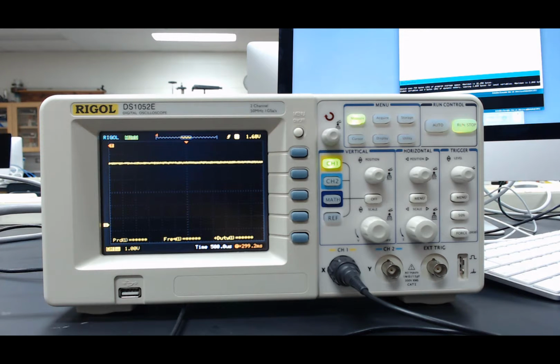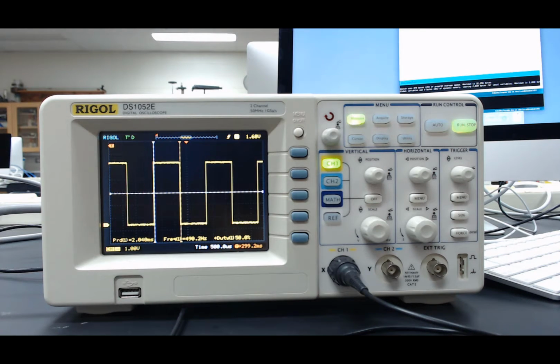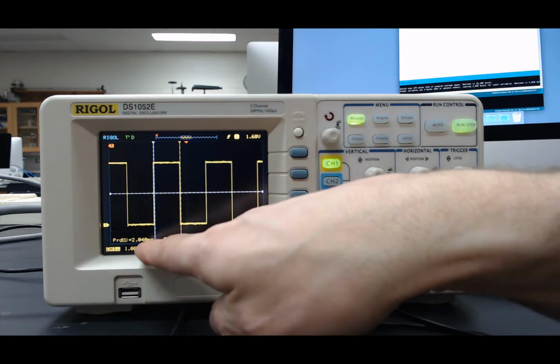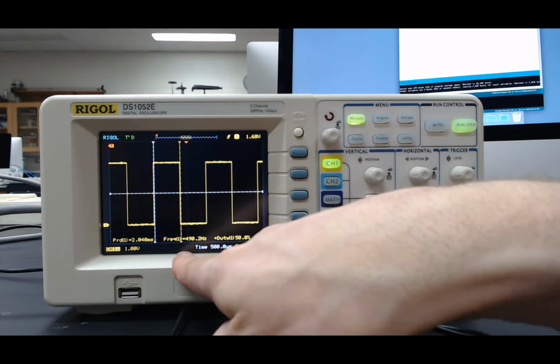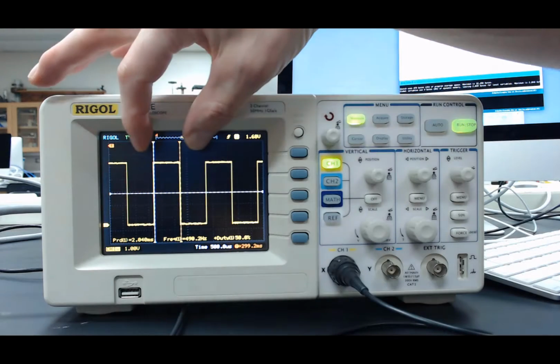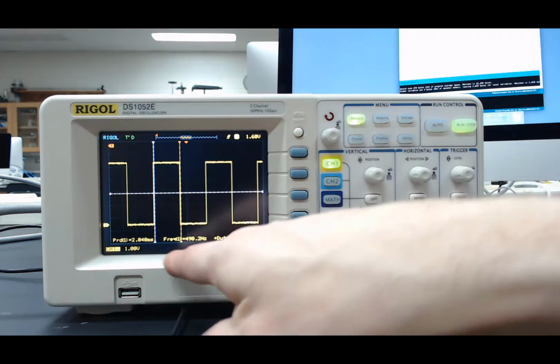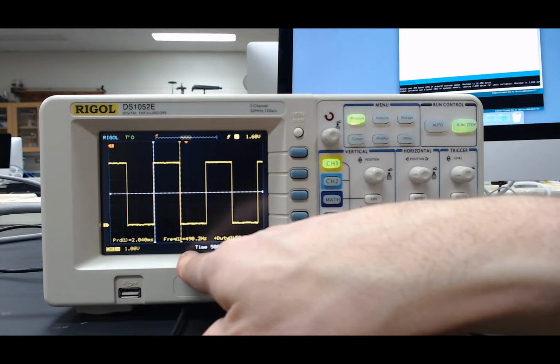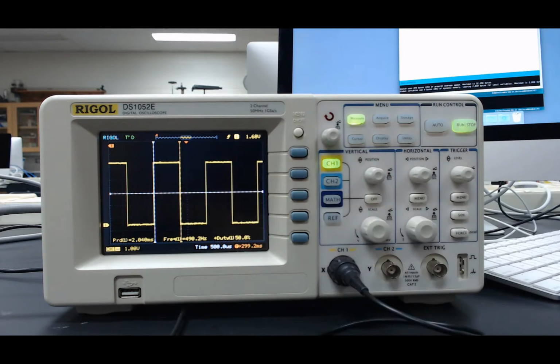And if I make it 127, which is halfway between 0 and 255, so that's approximately a 50% duty cycle, this is what the signal looks like. I don't know if you can see this very well, but I'm measuring the frequency of this signal, and it's a step function. It spends half its time high and half its time low, so that's a duty cycle of 50%, and the frequency is 490 Hertz.